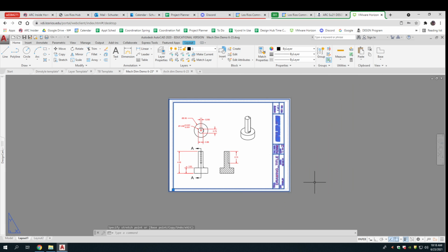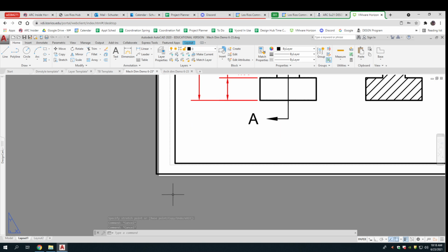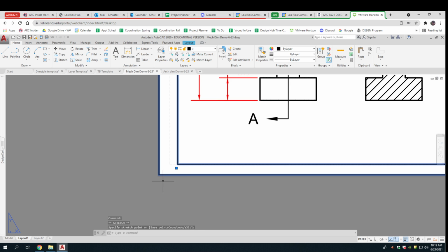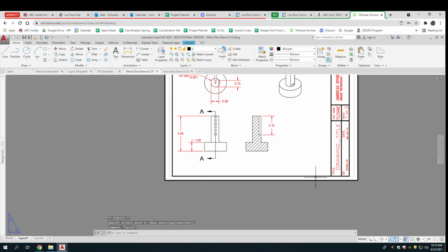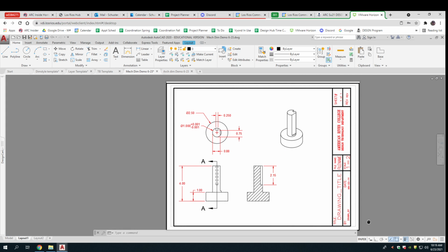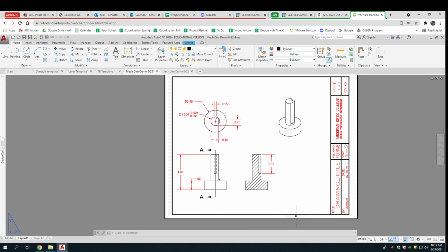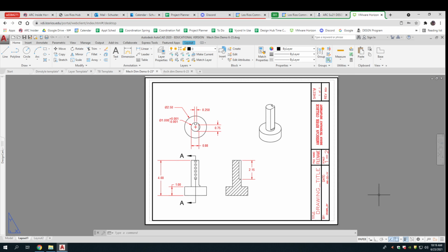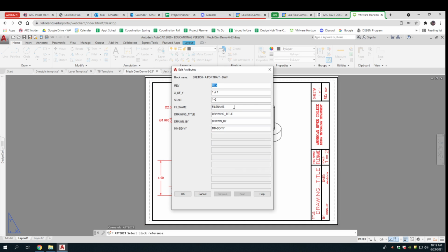And different pieces of paper come out differently. This outside thing isn't going to line up and show up. So I can actually move that. It fits right on it. There it goes. And depending on your printer, this is my printer margin. So it should show up okay. I can even move it a little more. So that's how I get a full one. And if I want to edit that, it's ATT edit. Click, and all this comes up.